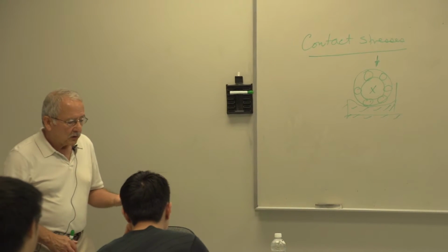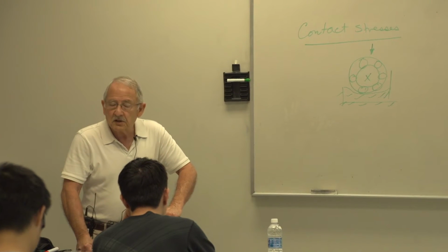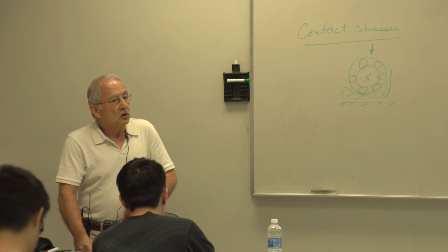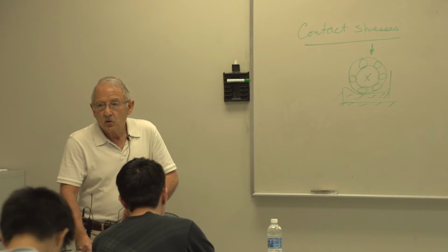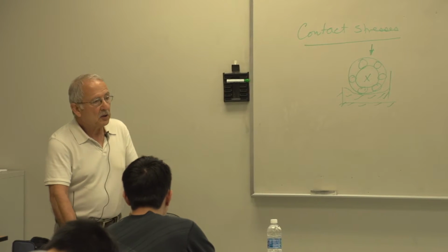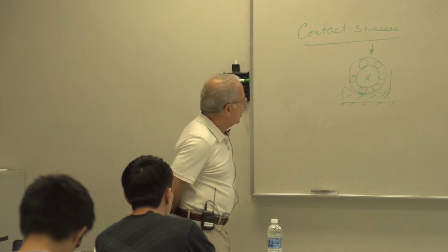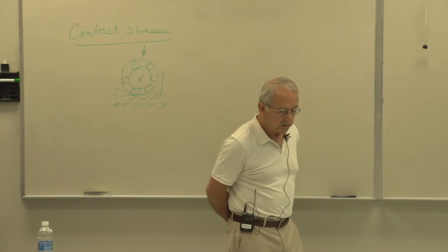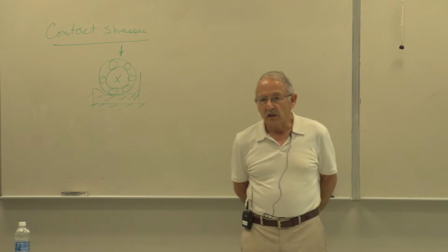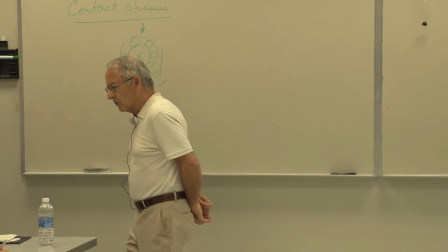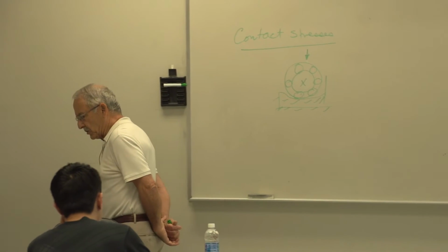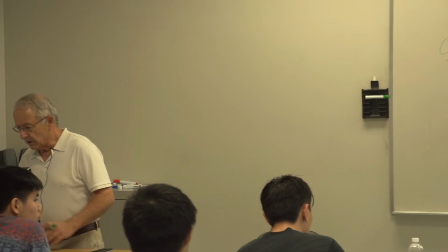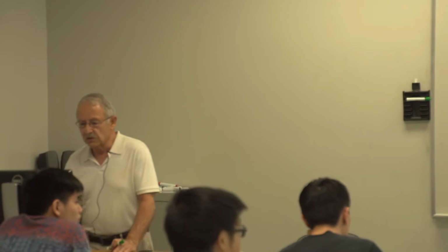These loads lead to stresses, which can lead to failure of the material, either by yielding or by a repeated process of loading and unloading, which is a type of fatigue failure. And we'll take a look at fatigue in general in detail. This one is a special case, so I'm just introducing it now because it is a part of contact stresses.